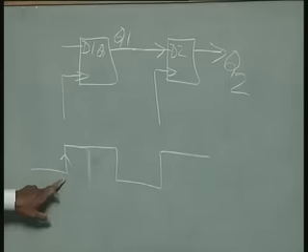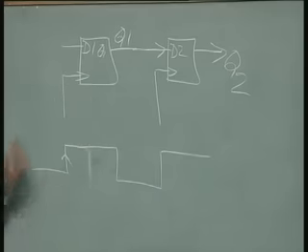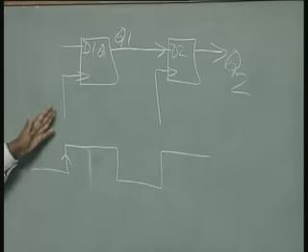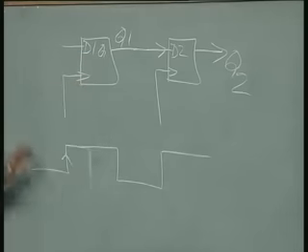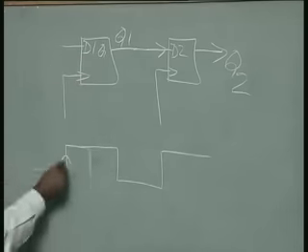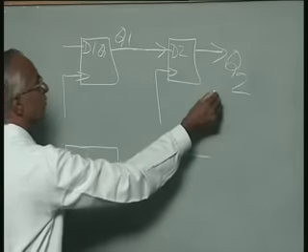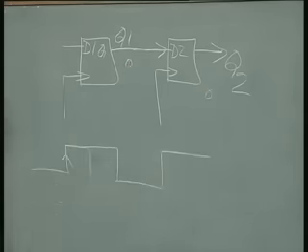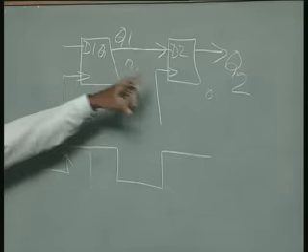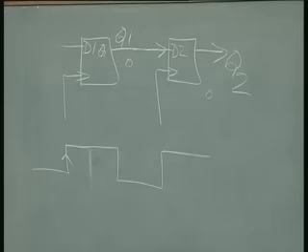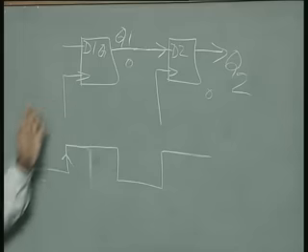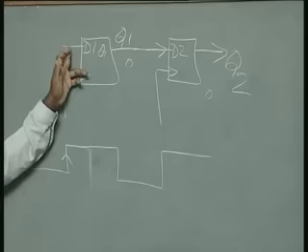Let us say at this positive edge, both flip flops will act. Whenever a positive edge clock occurs, both will act, and keep on acting. To start with, let us say even before this, both were zeros, for the time being. That is a reasonable thing because we started with the presumption that reset is applied always when the system is initialized. Now both being 0, suppose a train of clock pulses is coming earlier. Whenever the clock strikes, whatever is there here will go through.